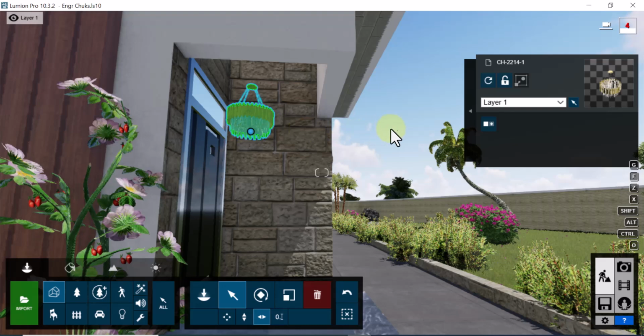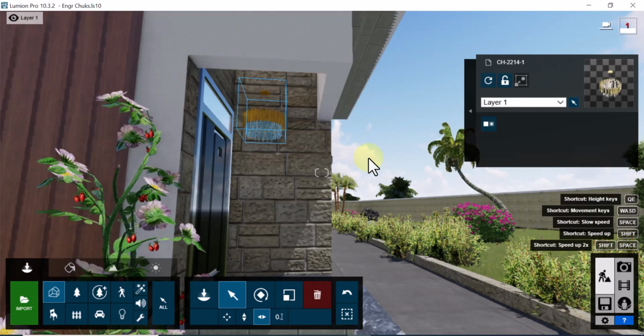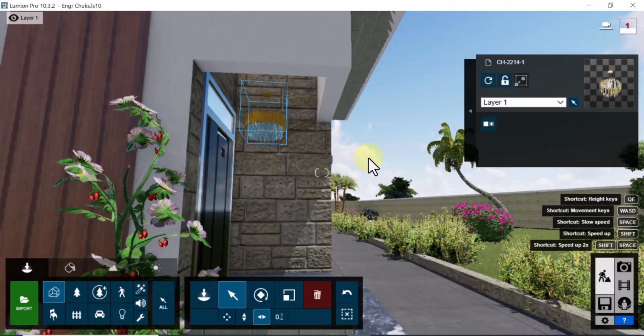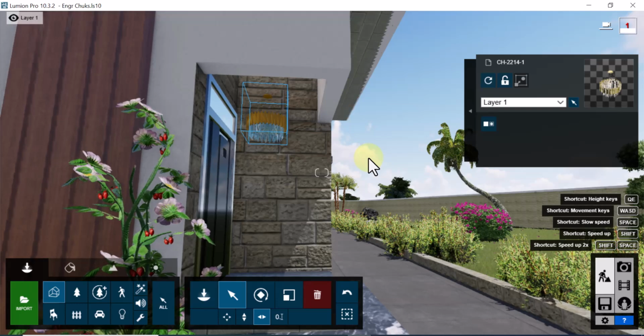Assuming I want to move it out a little bit, let's say I want to position it to the center. It's a question of holding my Z and moving it this way small. Z and X will help you to constrain your movement to horizontal axis. Okay, it will move either to the left or from front to back, just to constrain it horizontally.